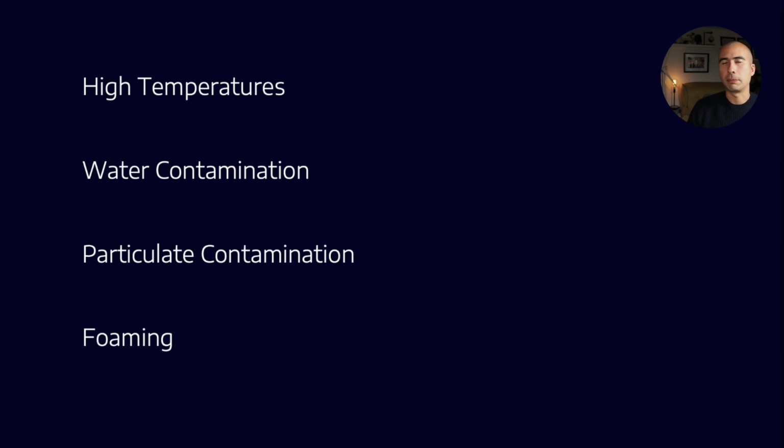And we also have foaming. And this is part of the nature of how gears are lubricated, in that it's either splash lubrication or maybe it's mist. Maybe we've got nozzles that are firing lubricants at the load area. So because of all these things, we're going to get a lot of entrained air, and there's often a lot of sloshing and movement of the lubricant around the gearbox. That can often cause foam.